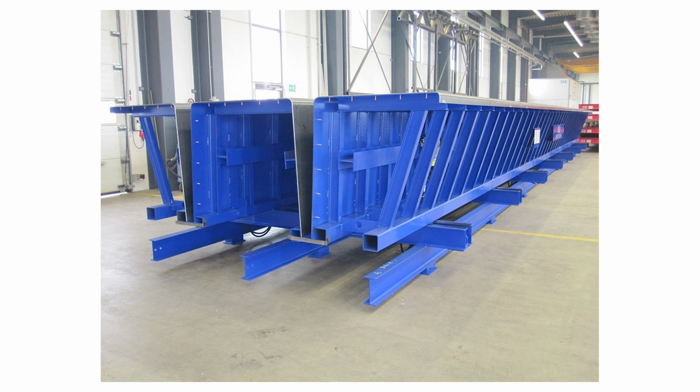Basically, first thing is the mold planning, where hollow cores are manufactured in the factory and where the T slabs are manufactured. T slabs have a web portion, so that has a very particular thickness, a lot of particulars in that T slab, so that's why T slab is not so common in manufacturing. But hollow core is just plain. It has a hole.